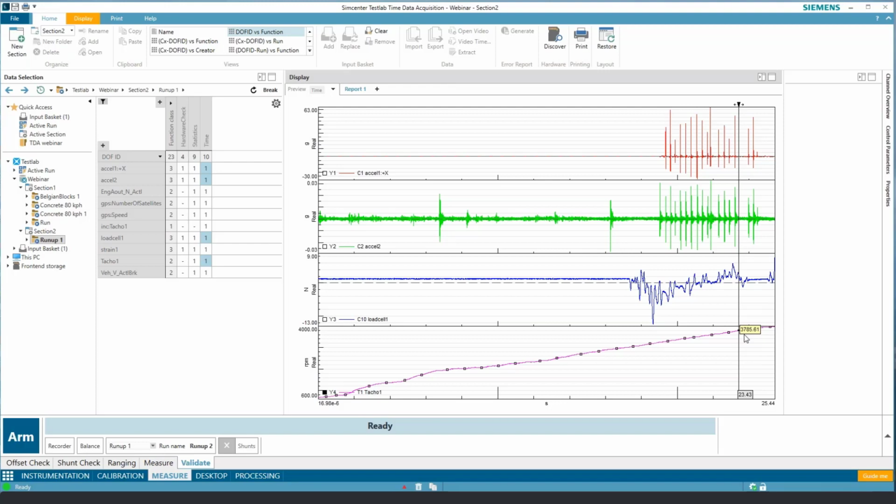Okay, so that gets appended on after the 3,800 RPM. And if I move the cursor here to 2 seconds, this is where we're passing through exactly 1,000 RPM because I also asked for 2 seconds pre-start. So that's the idea of pre-start and post-stop time added to the measurement.